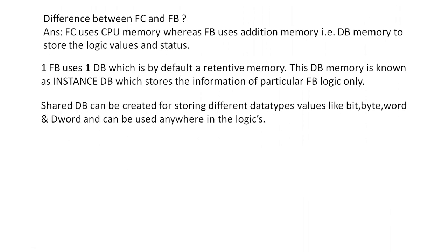Next, shared DB. Shared DB can be created for storing different data types, like bit, byte, word or double word format. Here also it is the same, because in FB also we are using bit, byte, word, double word addressing, for input addressing or for storing some memory. Here also it is taking different data types, but shared DB means you can share this in the total logic, in the total application, anywhere in the logic, just like we share MW, MD, bit memory, byte memory, in that way.